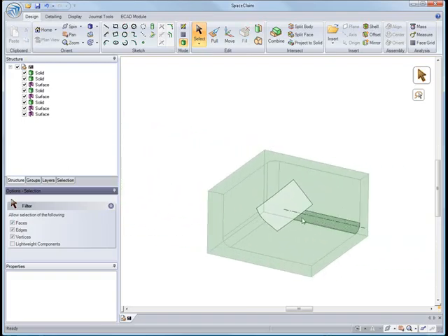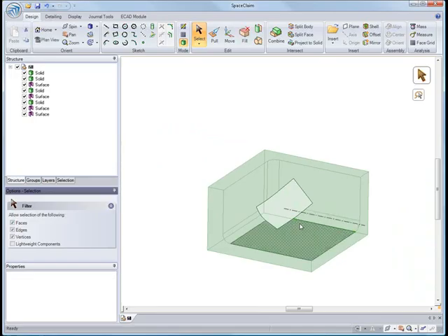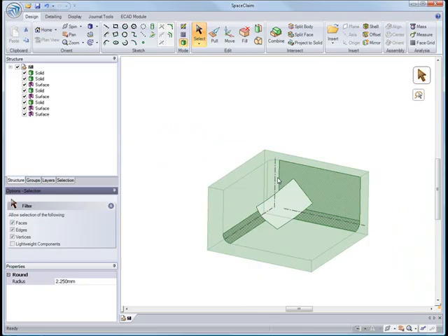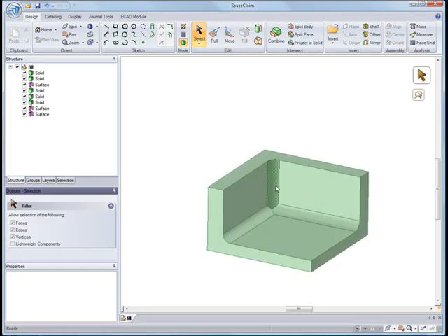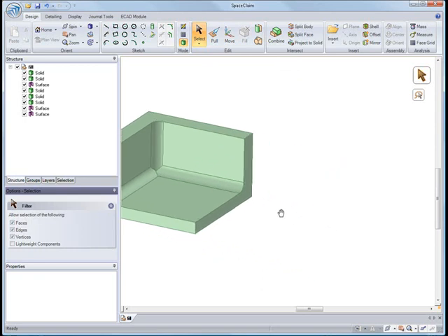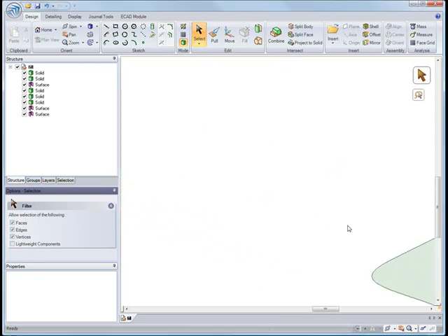In our next example, it looks like we have a solid with a surface missing. And notice there's three rounds that will intersect in that area. So even if we select on these edges here and hit fill, it simplifies it and fills it in and caps that surface while extending those rounds in together to create a solid where a surface used to be.